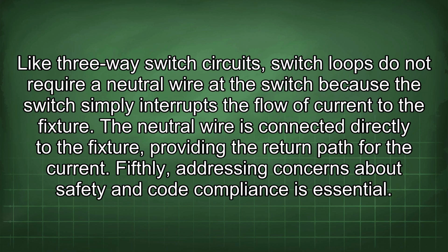Like three-way switch circuits, switch loops do not require a neutral wire at the switch because the switch simply interrupts the flow of current to the fixture. The neutral wire is connected directly to the fixture, providing the return path for the current.